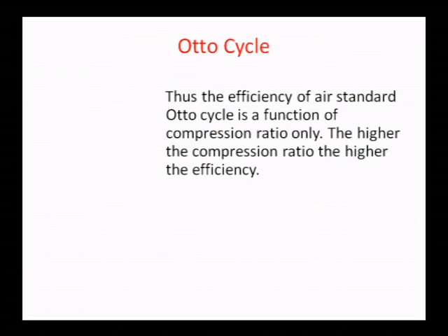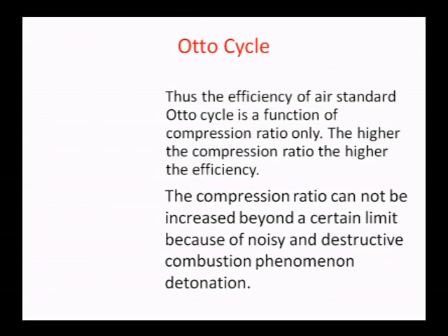The higher the compression ratio, the higher the efficiency. But you cannot increase it beyond a certain limit, because of the noisy and destructive combustion phenomenon known as detonation. So it can be increased only to a certain limit. Beyond that limit, it will become noisy and detonation will occur.